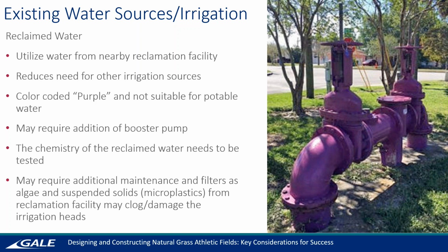Again, depending on the condition, you may need a booster pump similar to everything else, and you have to check the chemistry of these. Depending on what is leaving the site, it might be high in nitrogen or phosphorus, or the pH level might be off. So if you're going to be using reclaimed water, you want to make sure what the chemistry of that water is, because that will affect how you do your own fertilization and amendments as you maintain your natural grass.